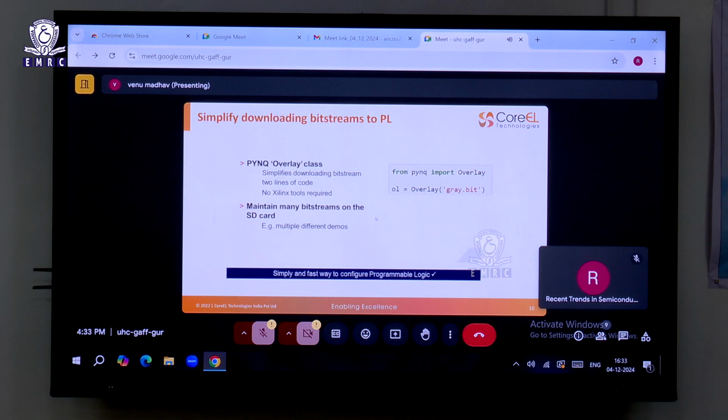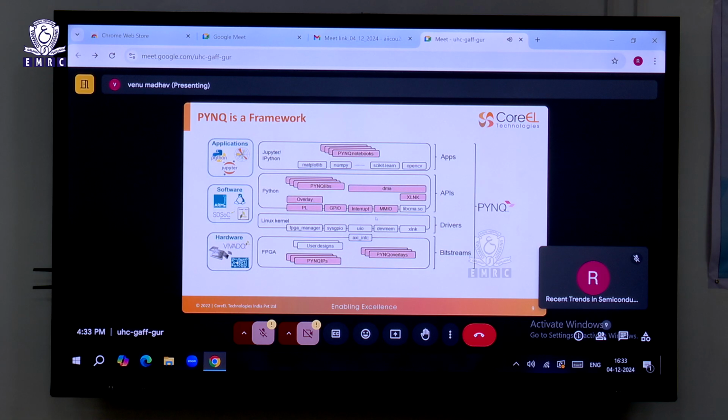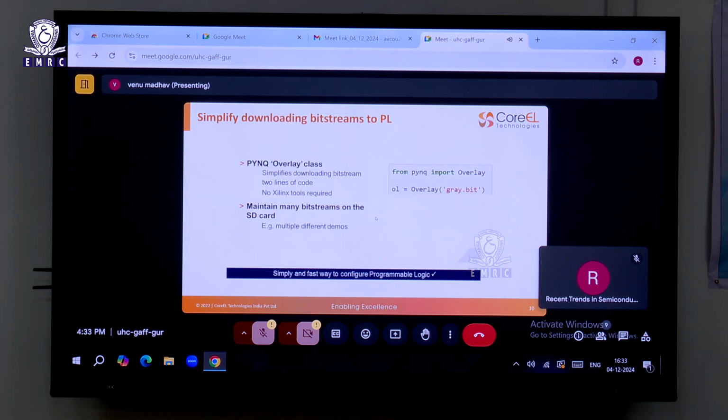Once we customize that, we can export it and save it on the board. We have seen here the base layer is a bitstream, right. That bitstream can be loaded in our program and we can work on that particular bit file. It is called bit file overlays, using overlays to input bitstreams.